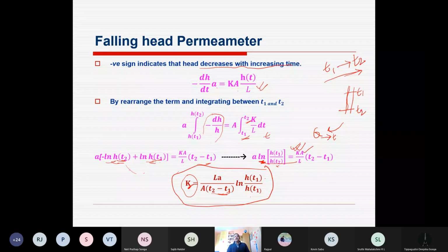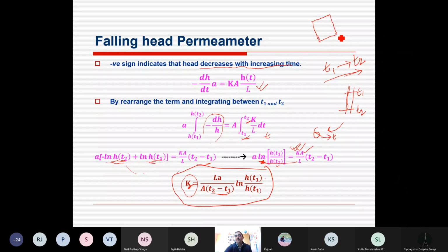So in laboratory condition, we need to collect the sample from the soil by using the core. Core means it's a cylindrical shape of a certain diameter and certain length. We are pressing it inside the soil slowly so that soil is not getting disturbed, and slowly it is taken out from the soil after cutting it, so that we are getting undisturbed soil.